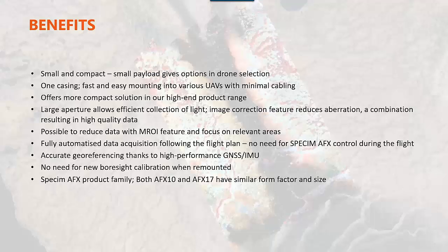We have an ability to reduce the amount of data by using the multiple region of interest feature and focus on relevant spectral areas. Data acquisition on AFX series is fully automated and it's following the flight plan, so there's no need to control the Specim AFX during the flight. We simply set the camera parameters and upload the flight plan before the takeoff, and after that the system acquires the data automatically when the drone flies according to flight plan.